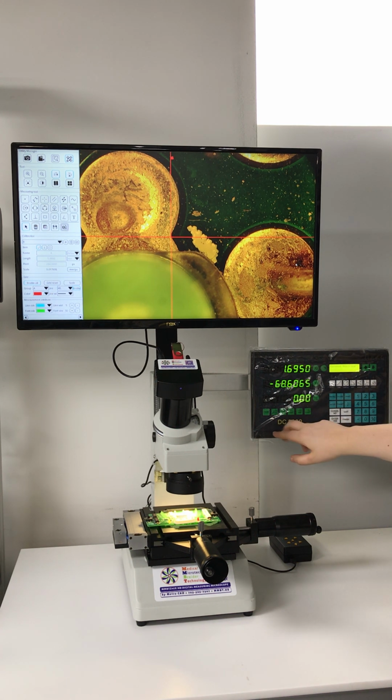As for the other buttons, you can program them if you have specific measurements that you want to take. Auto, manual, and edge detection is for if you have a camera sensor lens, but as we will be using the crosshairs, we will not be using these buttons. This is for increment or absolute value, and this is to change from polar to Cartesian. The polar will go from one measure from a point of origin, while the Cartesian will measure from X and Y.